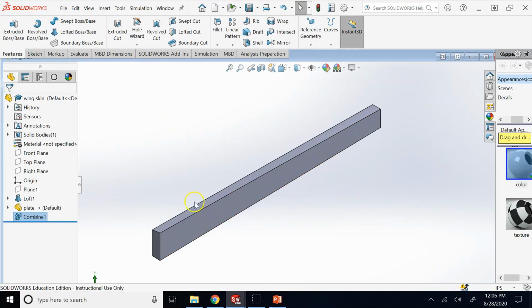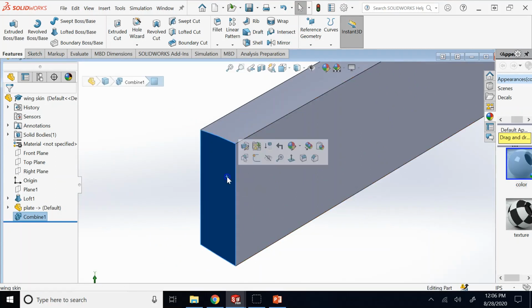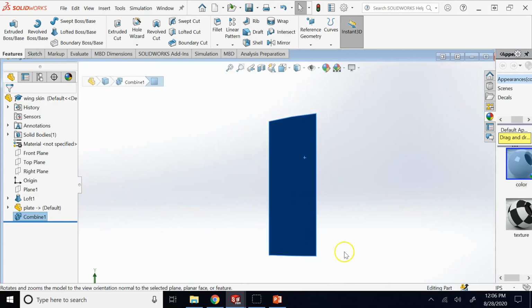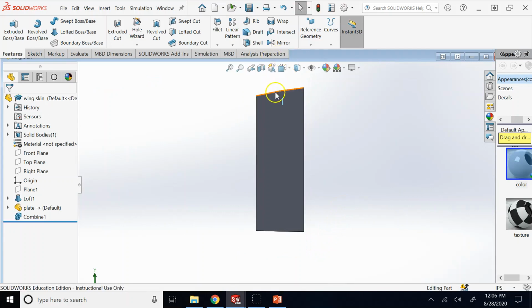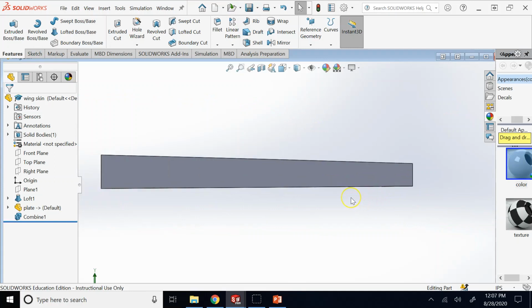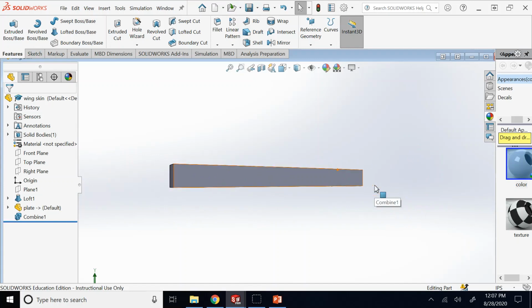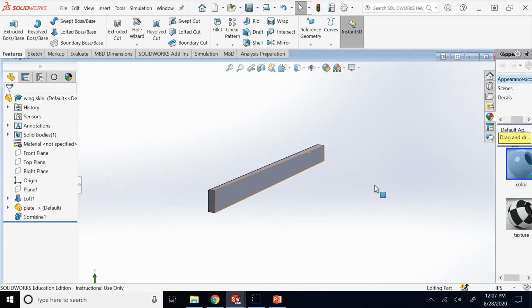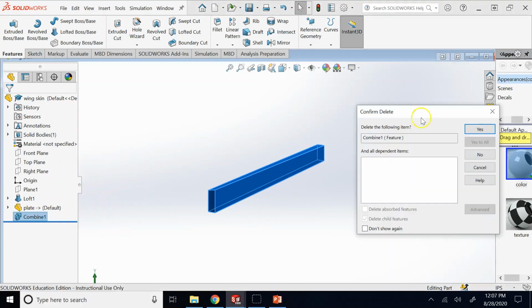Right? So again, as you can see, the profile is not perfectly rectangular. You clearly see that. A spline here, a spline here, straight, straight. And when you look at it from the side, there is also a draft angle in different directions. So creating this is way easier to do by Boolean operations than extrude and cut extrude. Now let me get rid of this.